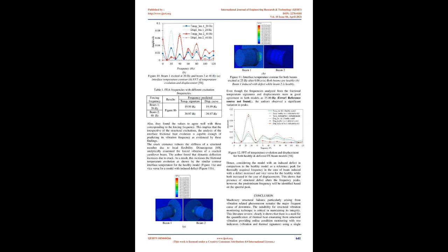In the case of 40 and 20 beam excitation for beam 1 and beam 2, respectively, the analyzed frequencies were 39.9686, figure 7a, and 20.000, figure 7b, for beam 1 and beam 2, respectively. Compared to the accelerometer measured frequencies, the relative difference was 0.28 and 0.20 for the former and latter, respectively. Similar findings were obtained by Talai et al. 57 in their work comparing infrared thermography and miniature deltatron accelerometer sensors in the measurement of structural vibration characteristics, finding that frictional temperature signature predicts the structural vibration frequency just as obtained from displacement.